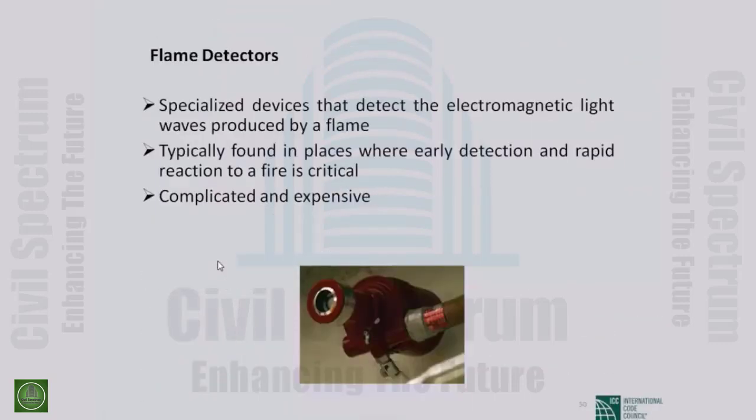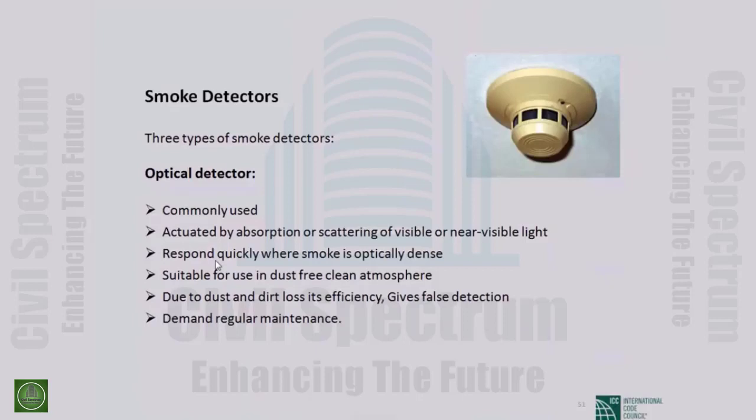This is a flame detector. It is not very convenient where line of sight is not available. If line of sight is available in the area, then it is very convenient. It is not a very costly thing. It will detect the flame light, so you need some line-of-sight position. Normally, though, line of sight is not very available.